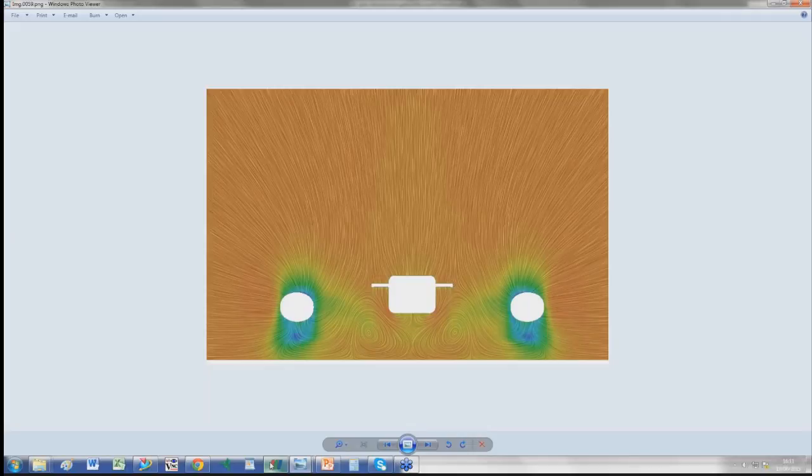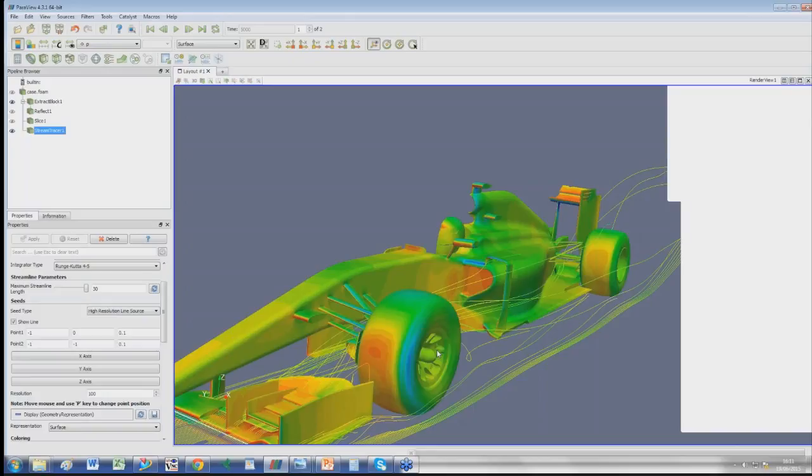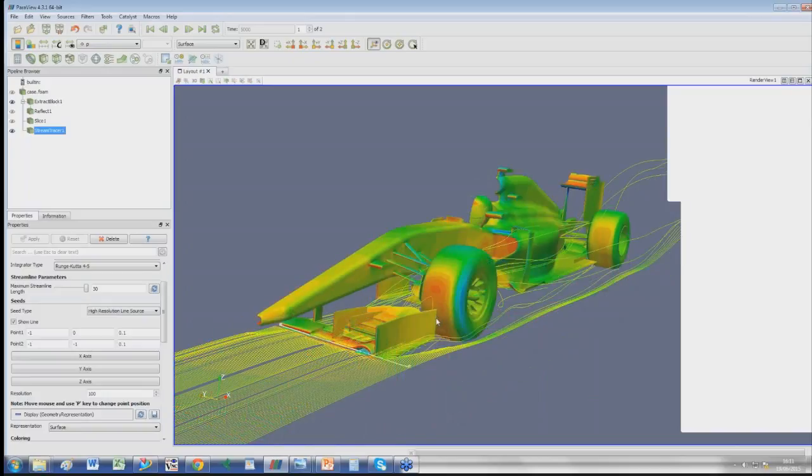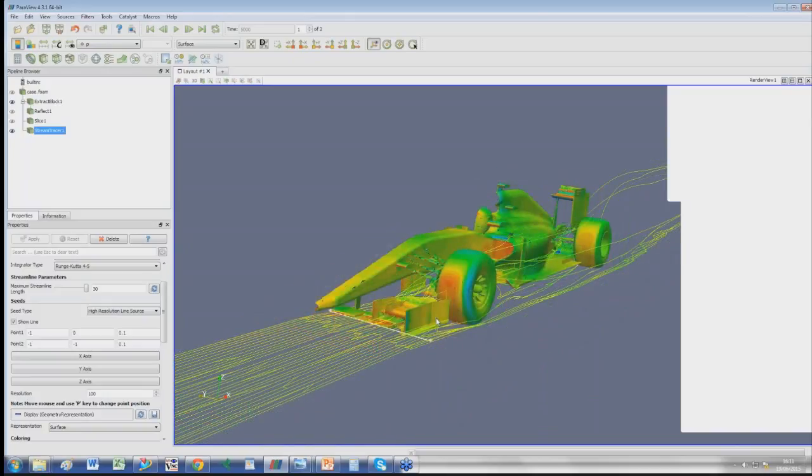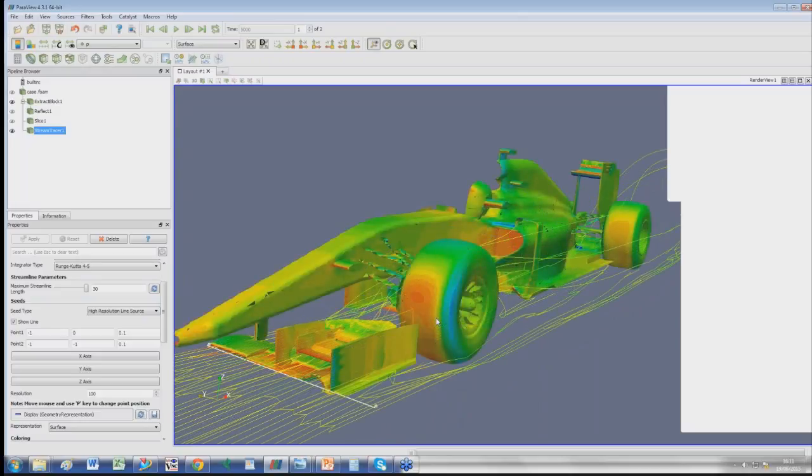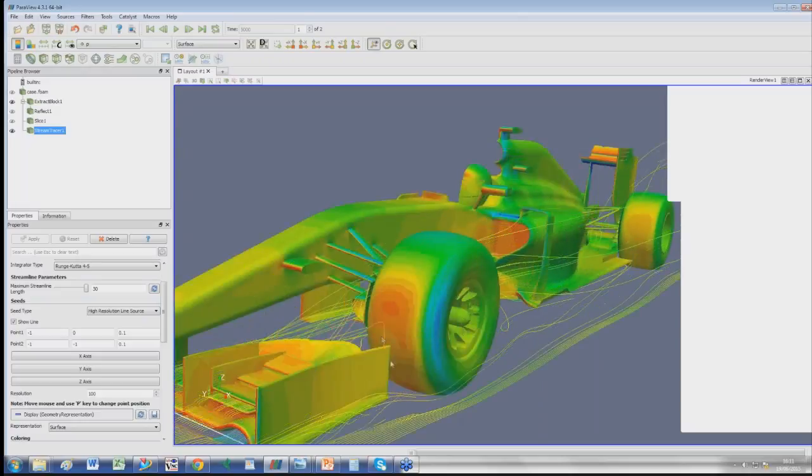This red zone is effectively creating drag on the car. You can see on the lower part, it's not as strong because we have this vortex effect. But we can even reduce the pressure even more by making the vortex stronger. So yes, we do use it. Okay, I think that is a good answer for the question.